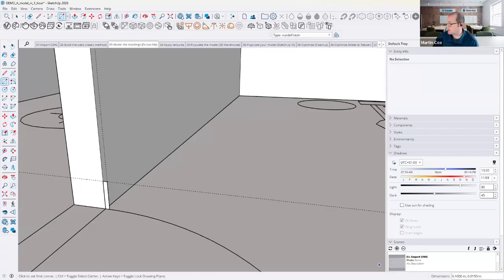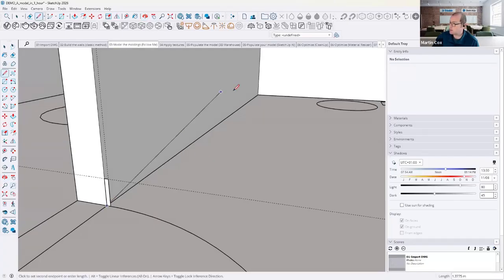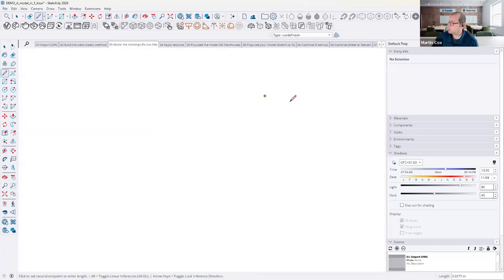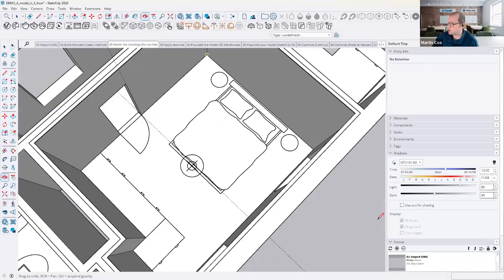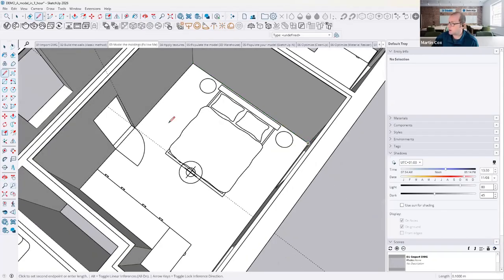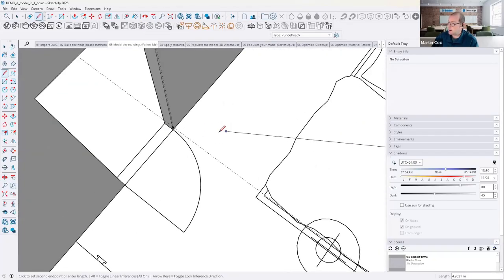And we can actually see those dimensions there. I know I did it in millimeters, but it's great to be able to mix. And then draw my line, use the Follow Me tool, and we can do that quickly from here. So if I go to the end there, let's just view out a little bit. This is something, again, you do get used to when you're working. We'll go along there with my line.